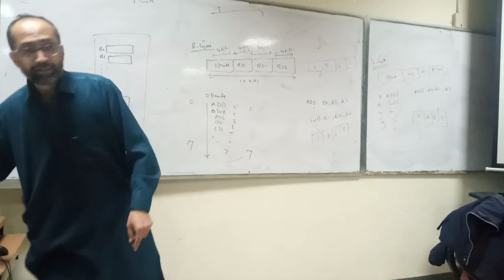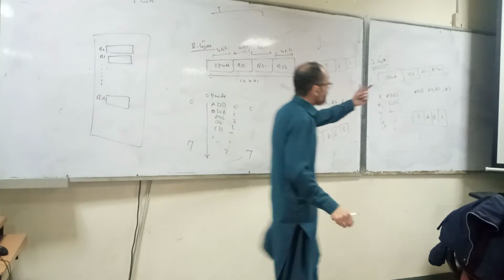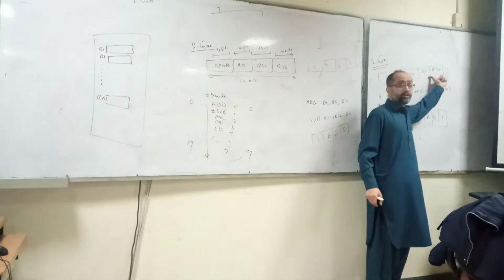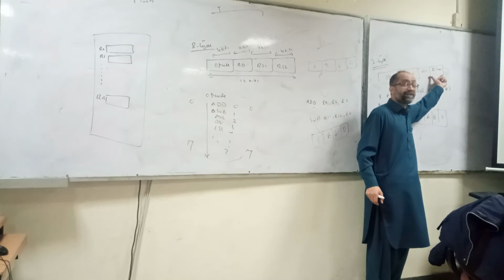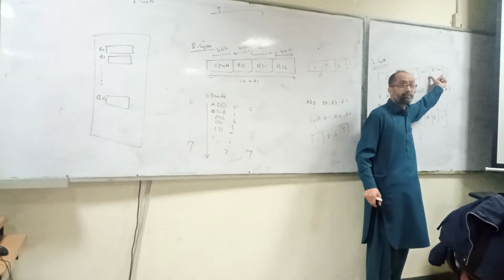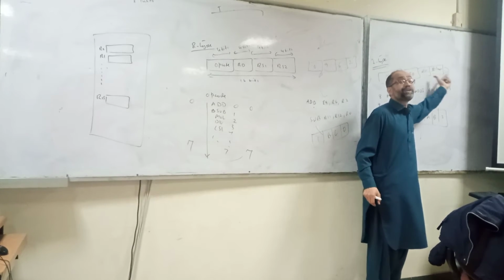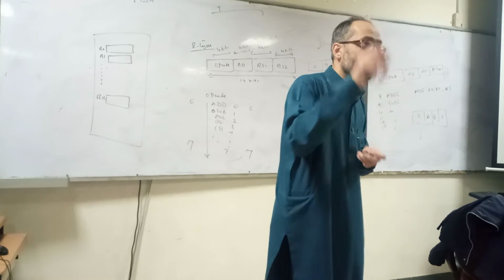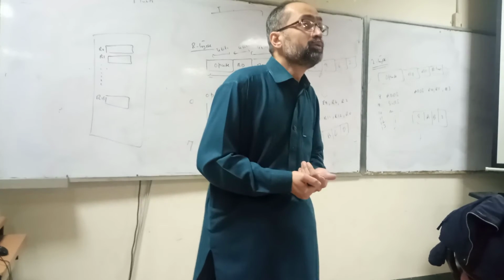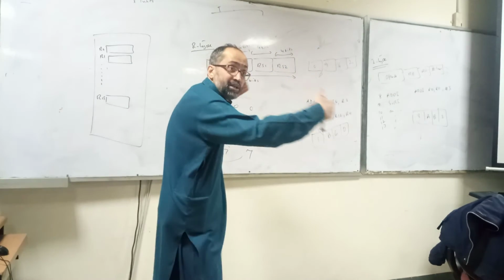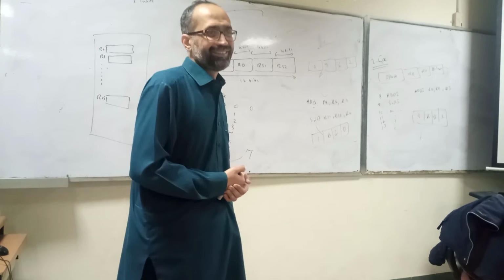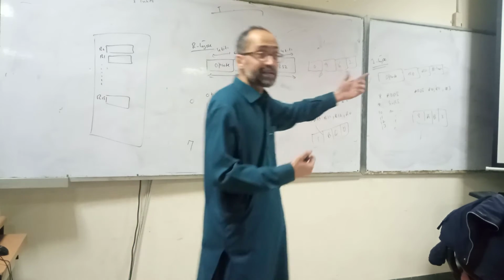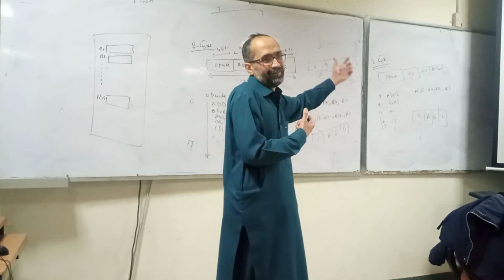okay, now in this limitation, what is the maximum size of the immediate operand that we can add? The maximum in this particular example is 15. We can add a maximum value of 15. But if you want to add a larger immediate value, what do we need to do? We need to increase the size of the immediate field of the instructions.